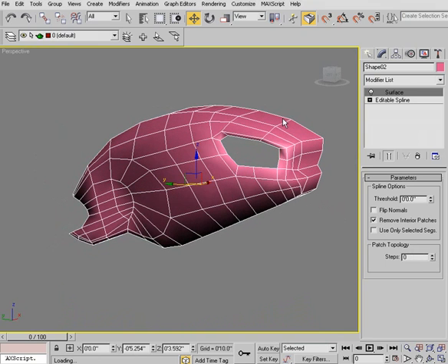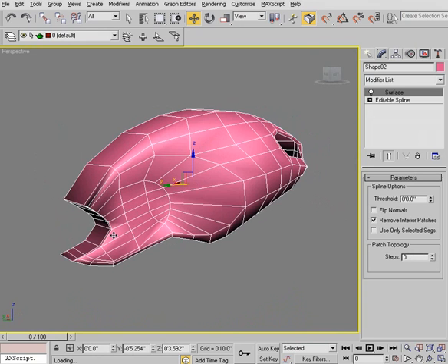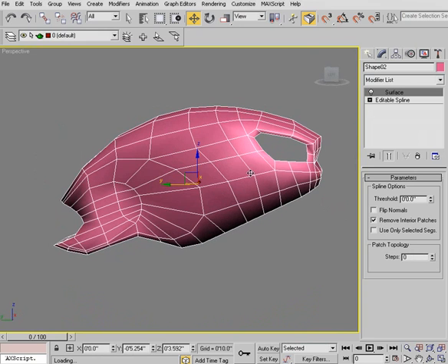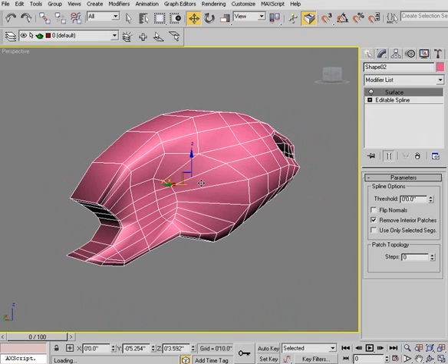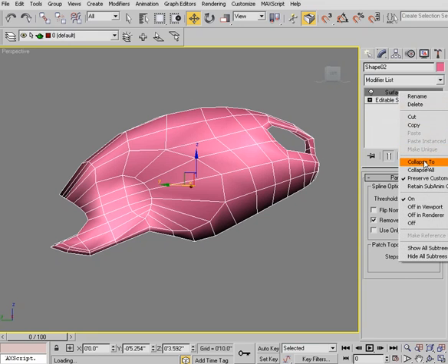All right, so once we've got this surface and it looks okay, you might have some holes or gaps, not counting this one. You can go ahead and just draw those across. You may have a big n-gon there that you need to fill in. You may have some segments you need to delete and redraw across there. Any of those sections will show up as not having any geometry there. You can fix those up by deleting those segments and then refining those again. All right, so once we've got this, we can go ahead and collapse the stack.